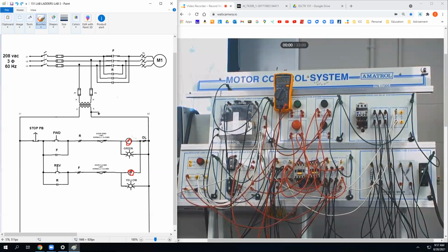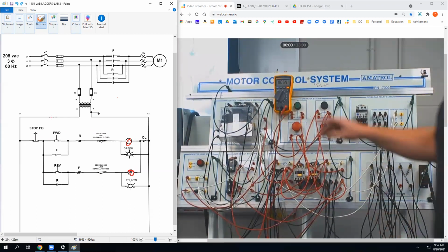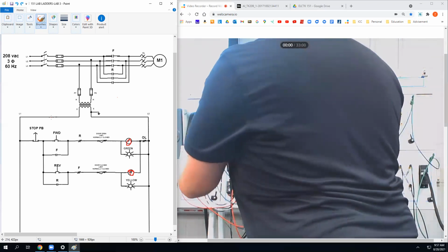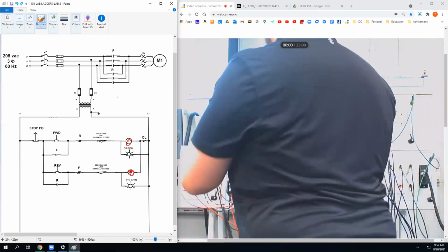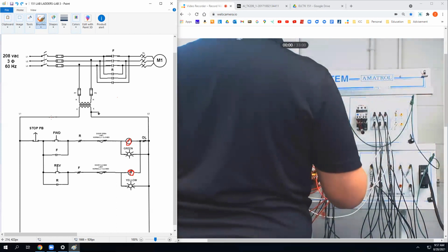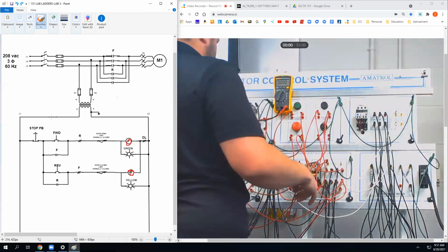By the book, we would check the coil, then the limit switch, then the blah, blah, blah. But the only thing that's in series with all of that, because Heath's so smart, is the stop button. So let's check there. Maybe I should just shut up and let you guys do it. Why is this? What the? Could that be the problem? Well, it was working before I put a fault on.